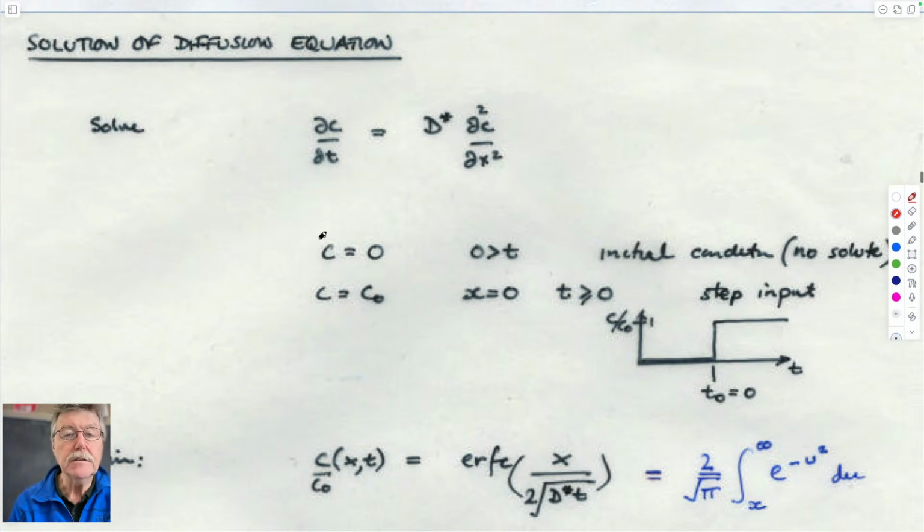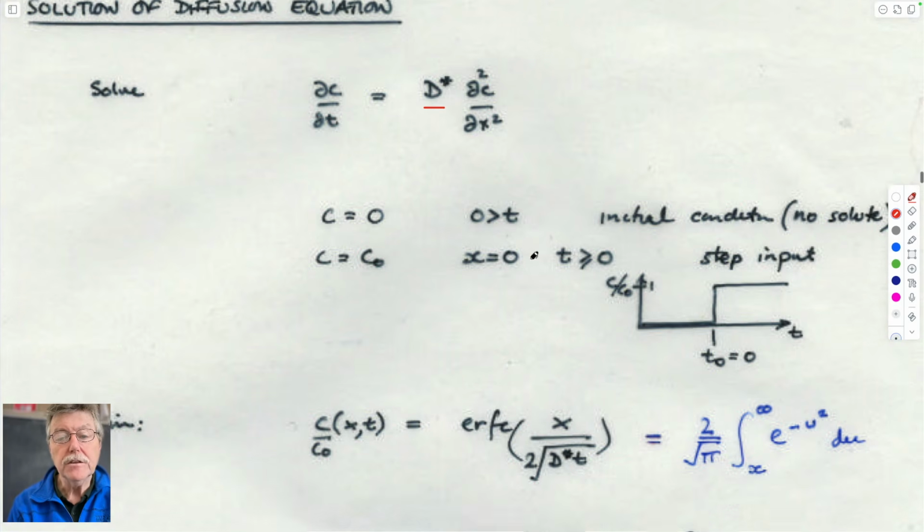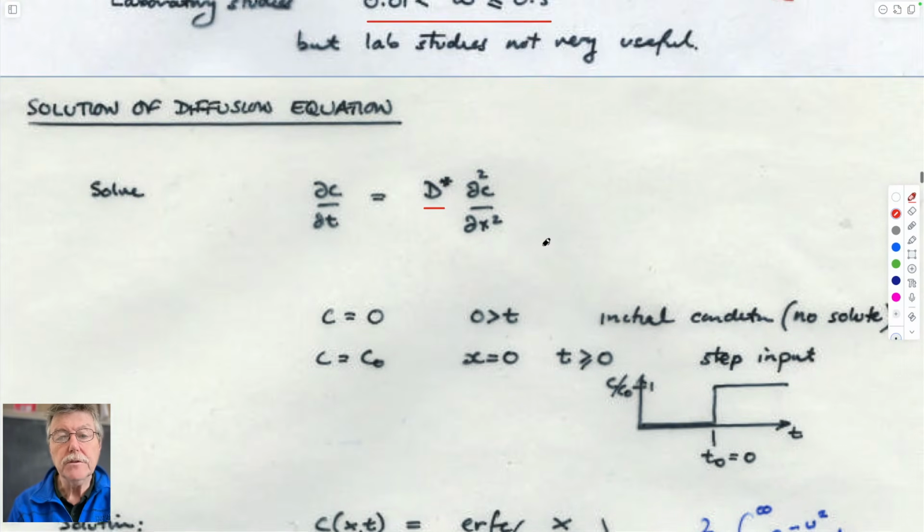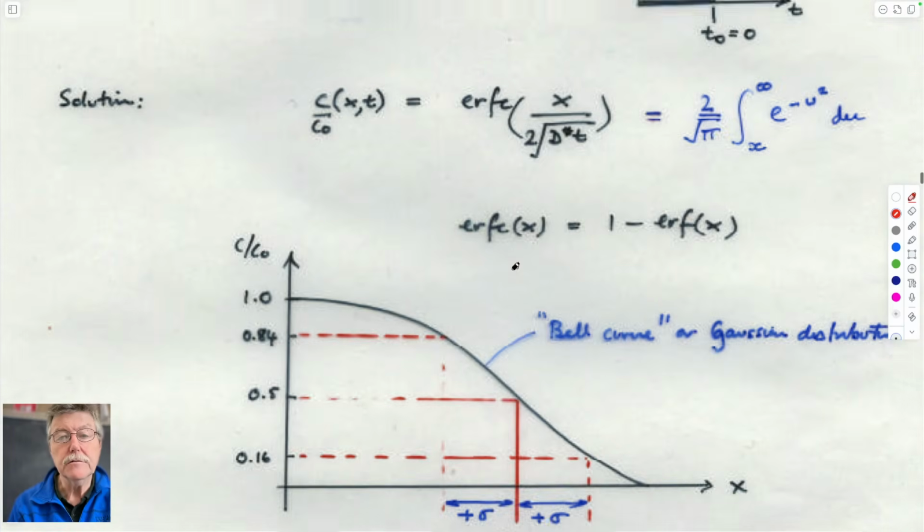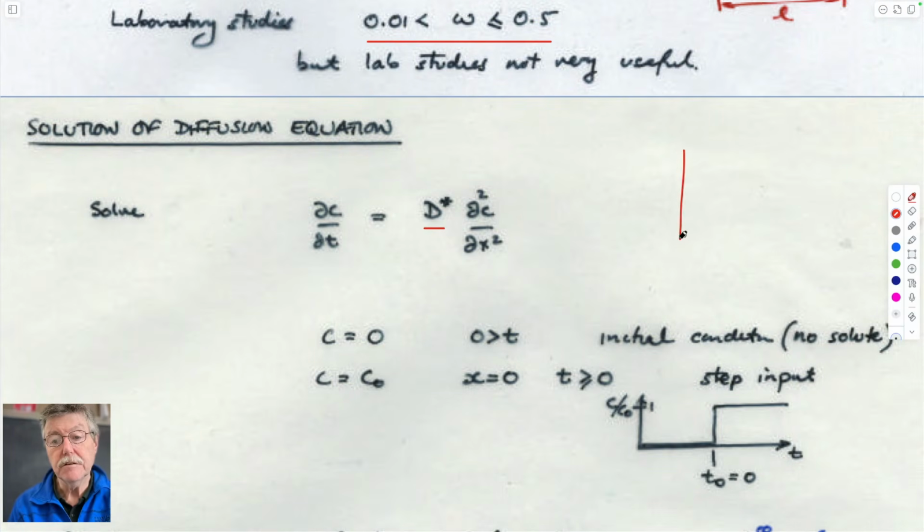And so we can solve this equation with the effective diffusion coefficient, and we can solve it for a geometry, the one we've drawn before. The geometry would be this. This would be relative concentration, C over C0. This would be 1. This would be at time 0. This would be radius. And this would be the boundary conditions, or as we choose them.